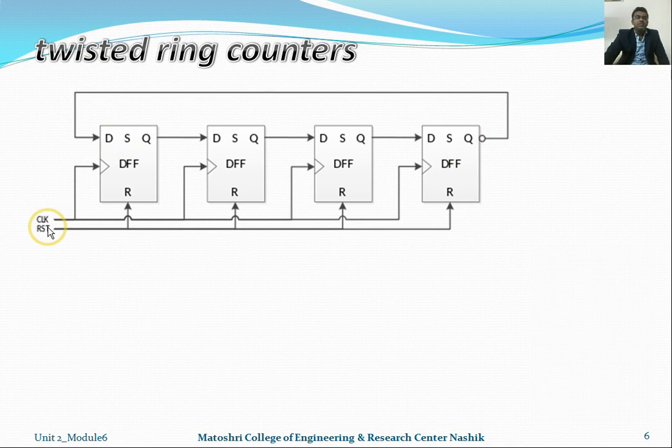Another change is that initially we reset all the flip-flops. Once we have reset all the flip-flops, we remove the reset pin and continuously provide the synchronized clock pulse. So for each and every clock pulse we get a different output state. We have to see it in detail one by one.